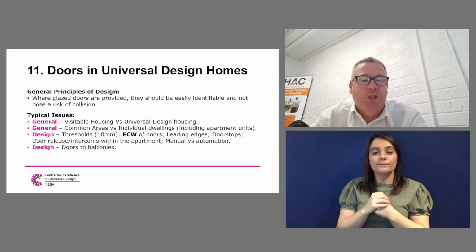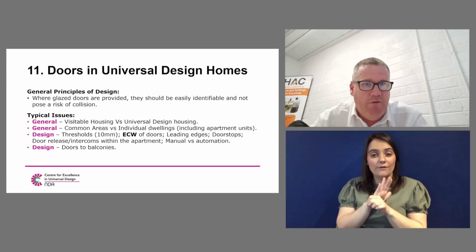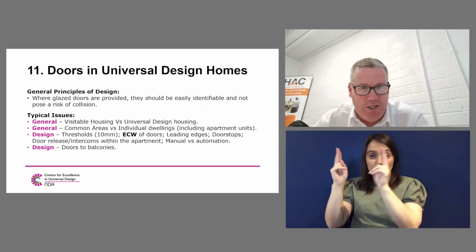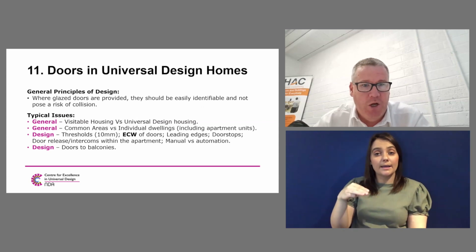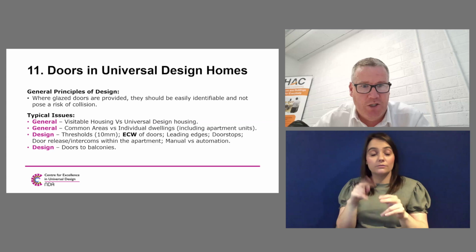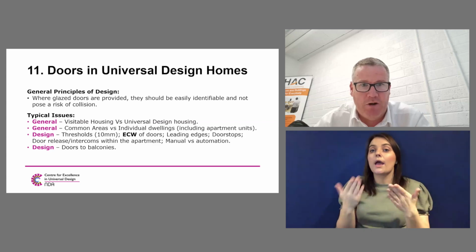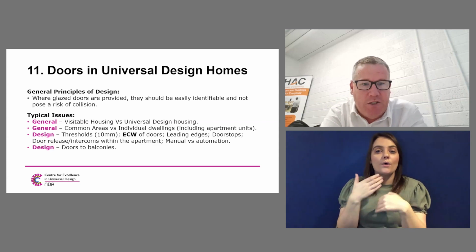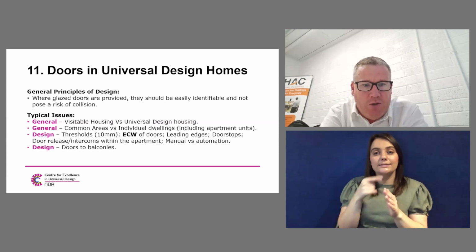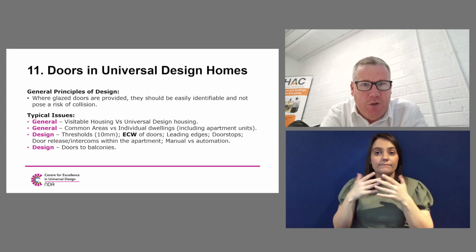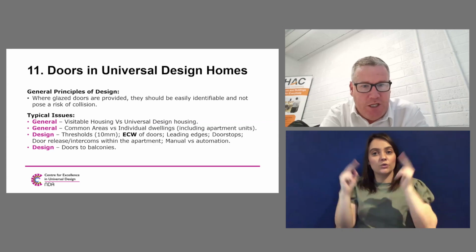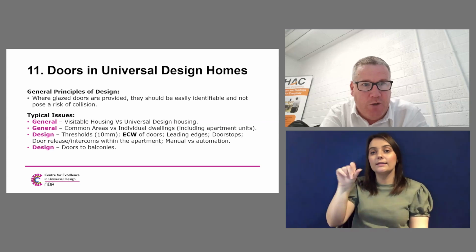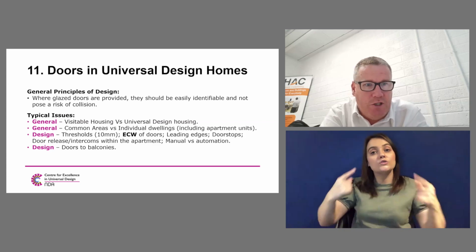So I suppose just to watch out for in relation to visitable housing versus universal design housing. So Part M requires that a house is visitable for someone with a disability, whereas good practice now relates to universal design homes, so that we design houses that can cater for everyone. More and more county development plans and city development plans will require that a percentage of houses in larger schemes need to be designed to universal design home standards. And as mentioned previously at the start of the presentation, the NDA have guidelines, and so do the Irish Realtor Association, on universal design homes.